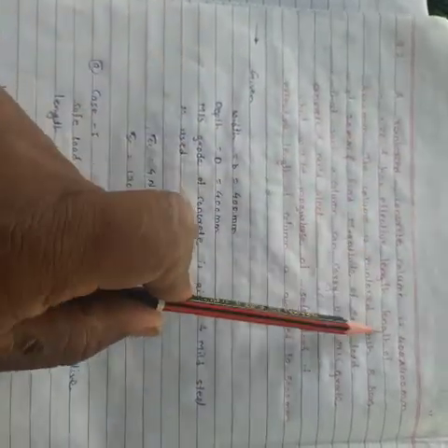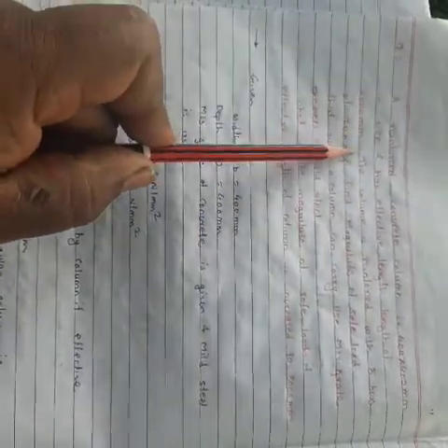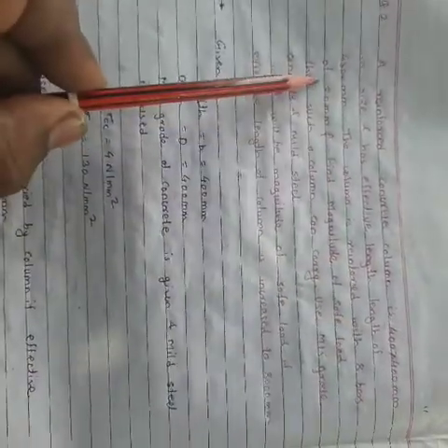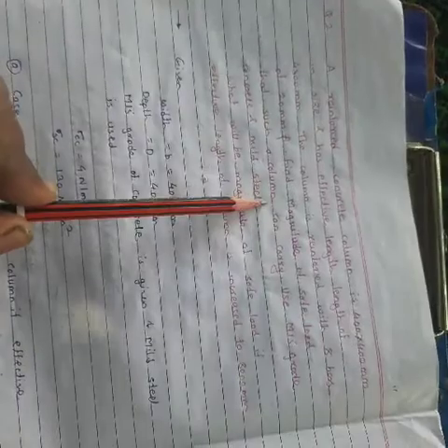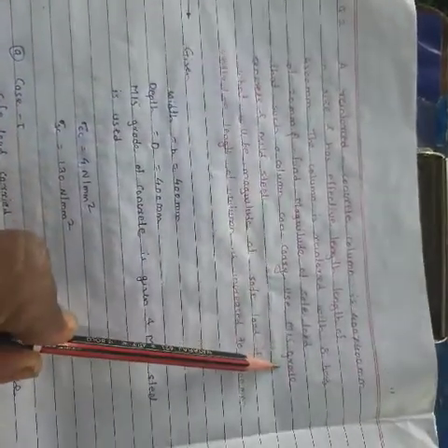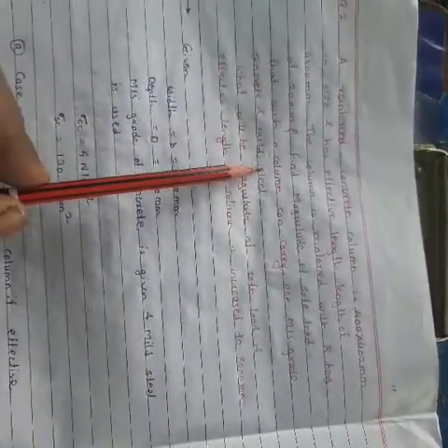Now we are continuing with the analysis of the column, that is, determination of load carrying capacity of the column. A reinforced concrete column is 400 mm by 400 mm in size and has an effective length of 4500 mm, and the column is reinforced with 8 bars of 20 mm diameter. Find the magnitude of safe load that such a column can carry. Use M15 grade concrete and mild steel.